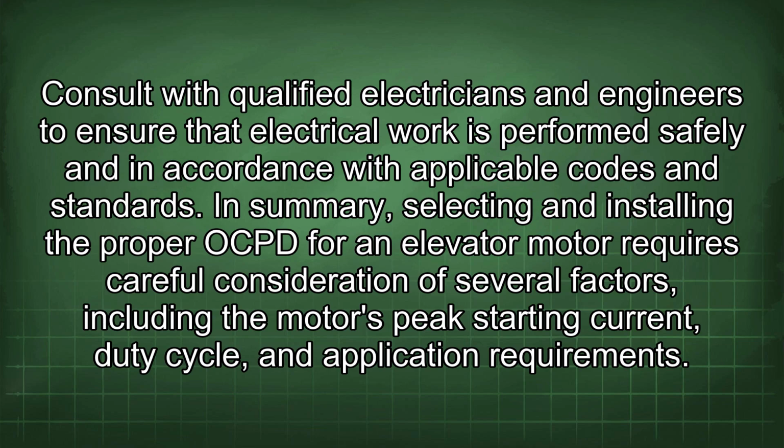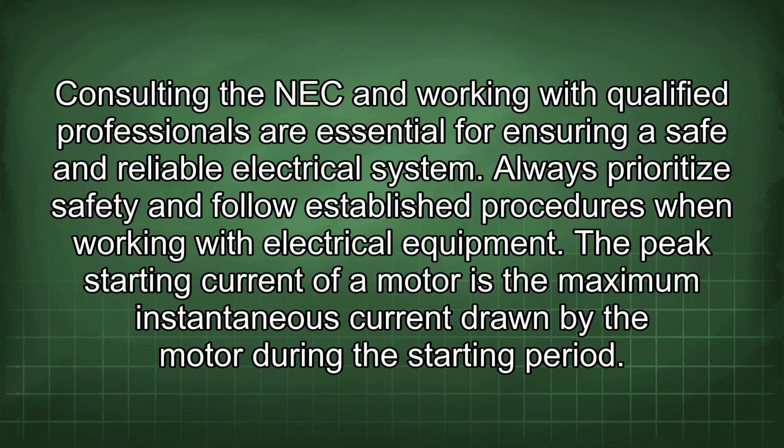In summary, selecting and installing the proper OCPD for an elevator motor requires careful consideration of several factors, including the motor's peak starting current, duty cycle, and application requirements. Consulting the NEC and working with qualified professionals are essential for ensuring a safe and reliable electrical system. Always prioritize safety and follow established procedures when working with electrical equipment.